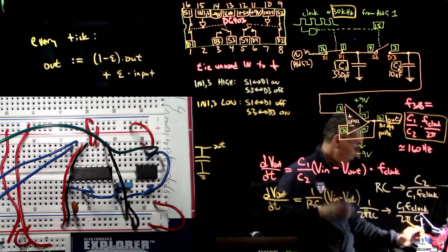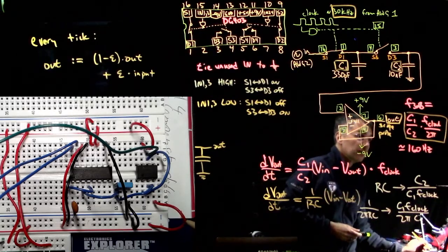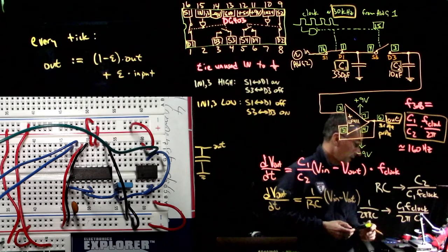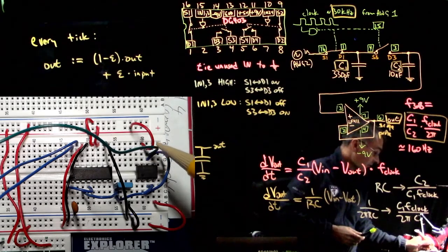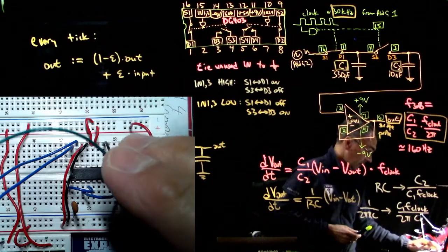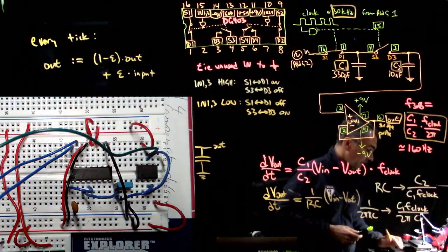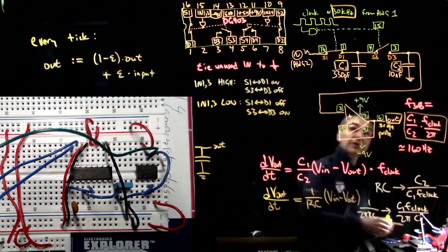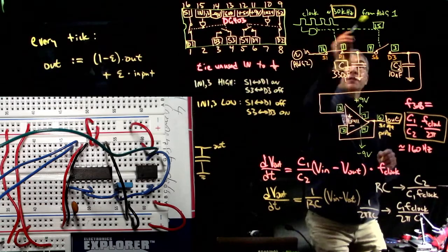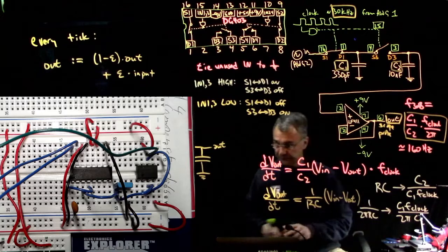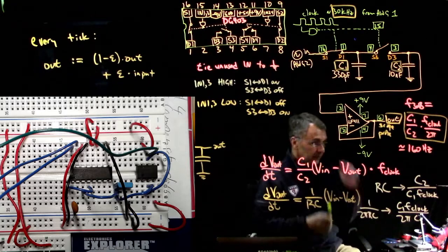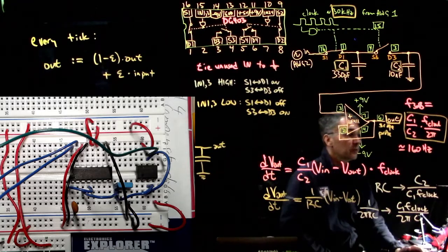Pin 4 is negative power, so here's pin 4 going down to -9. Pin 6 of the op amp is also our circuit's output, so that is going to scope channel 3. Scope channel 1 is looking at this 30 kilohertz clock, and scope channel 2 is looking at the input signal. Now, let's see what we get.